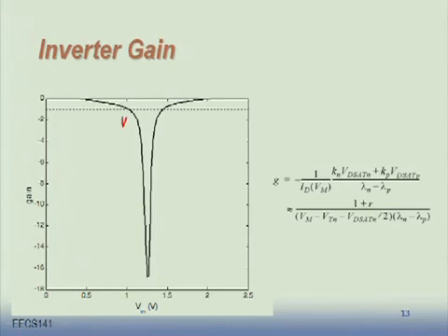This is VIL, this is VIH. Okay? And you'll find out that the numbers that you get from this plot versus this approximation that I've shown you, the differences are small because the gain is fairly high. This gain in the center is about 16-ish, 17-ish.